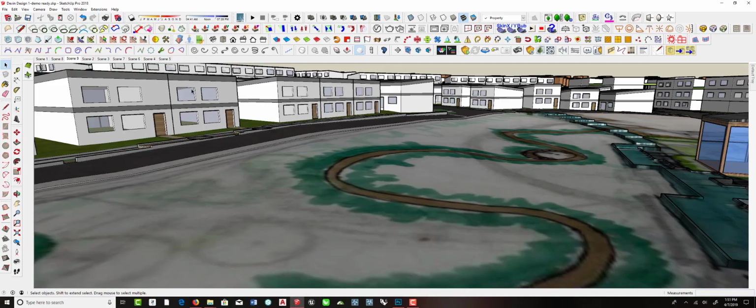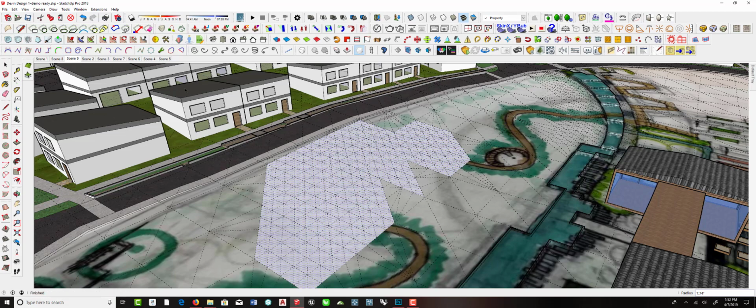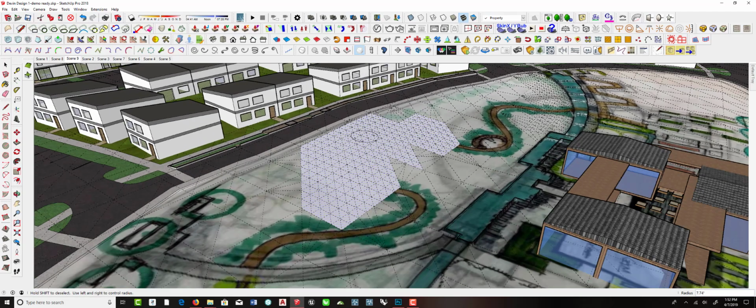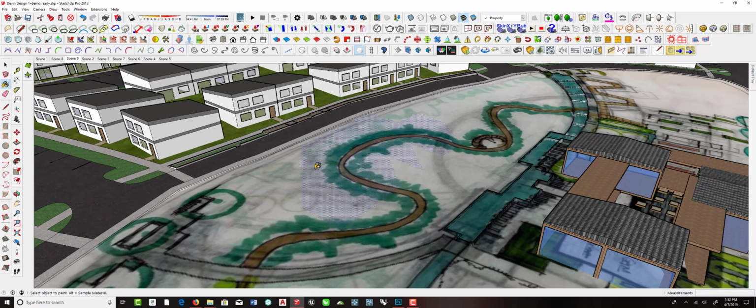It might work as a trail through the woods, but if we just turn the hidden geometry on, again, this is an area where I would use the Artisan Select tool and just select all these areas, and subdivide that, and probably subdivide it again. And I'll just focus on that right now. So again, turn the hidden geometry off just for a bit, pick up the pattern, place it back down. Let's go back to the sculpt tool, hit escape to get rid of that, and let's turn on the hidden geometry again.